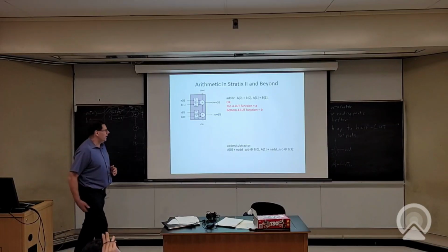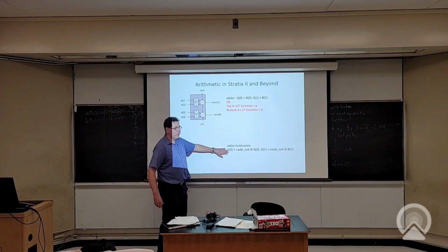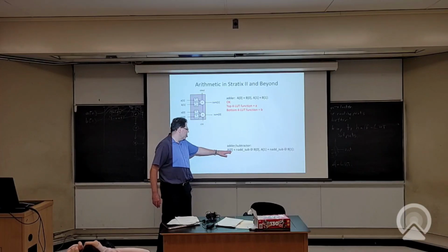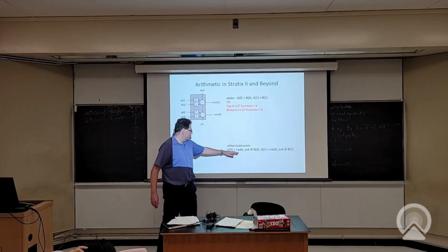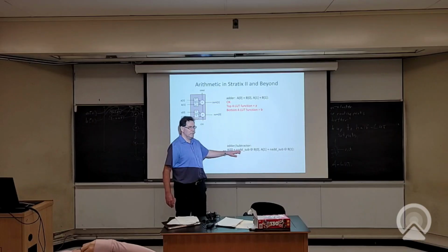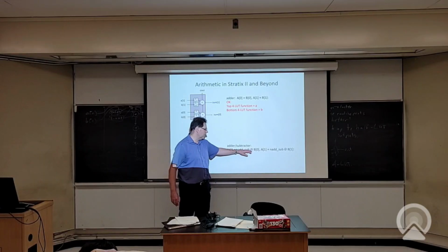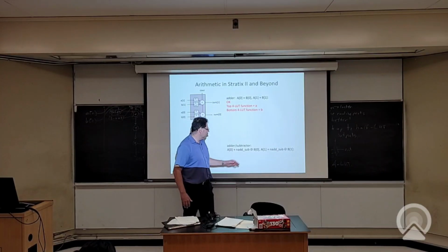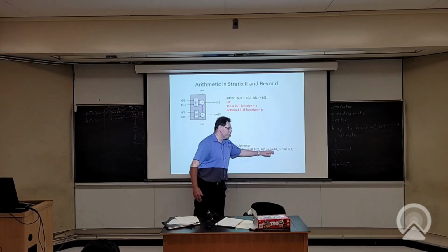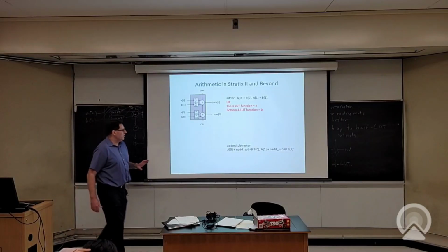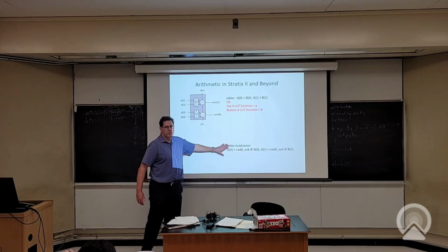An adder subtractor. So this is now not just a subtractor, it's a subtractor that can be an adder or a subtractor dynamically. So that function is take A plus an optional complement of B, right? So n adder sub means set the signal to 0 if you want to do an add, set it to 1 if you want it to be a subtraction, take the exclusive OR of it with B, so that basically is programmable complementation. Do that on every bit, right? Next bit is A1 plus n adder sub XOR B1. Can I fit this in this structure? So what do you think?